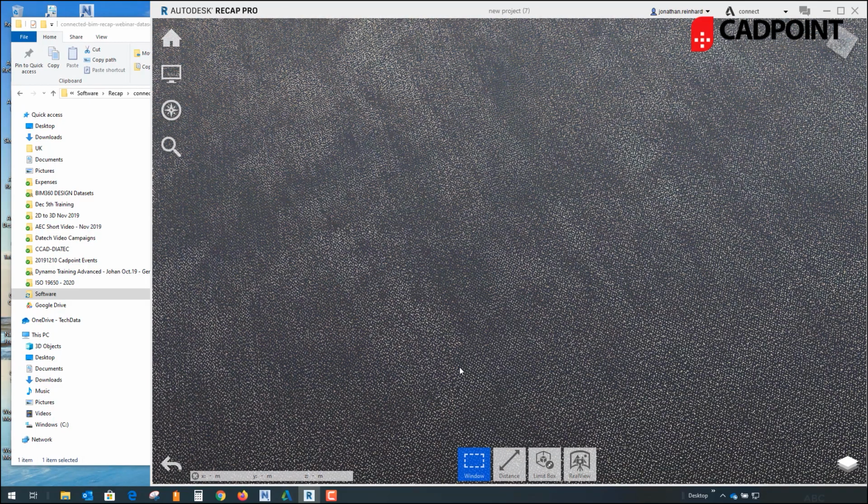Our decimation settings can be 0 millimeters. If you set that to 50 millimeters, you will only have a point every 50 millimeters, so every point will be 50 millimeters apart. You can set it to 5 millimeters, so every point is 5 millimeters apart. Everything within that particular square of 5 millimeters, there will be no points within there. So you can imagine it has benefits in terms of file size, but obviously you lose a certain amount of information. So just be conscious of that as well.